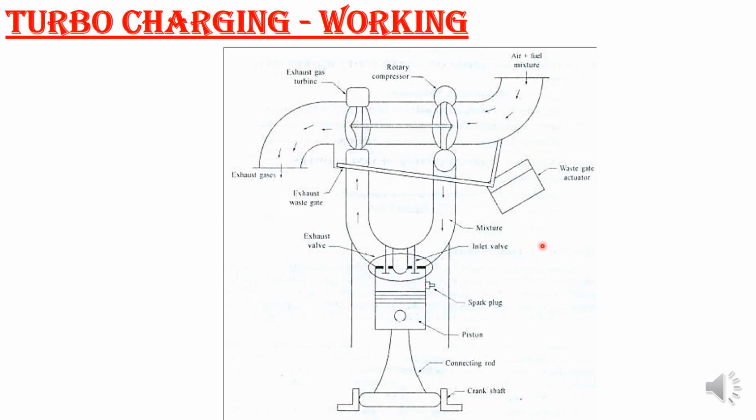Now we want to control this pressure ratio, say to 1.3. So how can you control it? You have to control the speed of this shaft. How can you control the speed of the shaft? You can give only a small amount of exhaust gas, especially at higher speed or higher load conditions, because a larger quantity of exhaust comes into the picture. Whenever more exhaust comes, more pressure is created and the rotational speed of the turbine will increase.